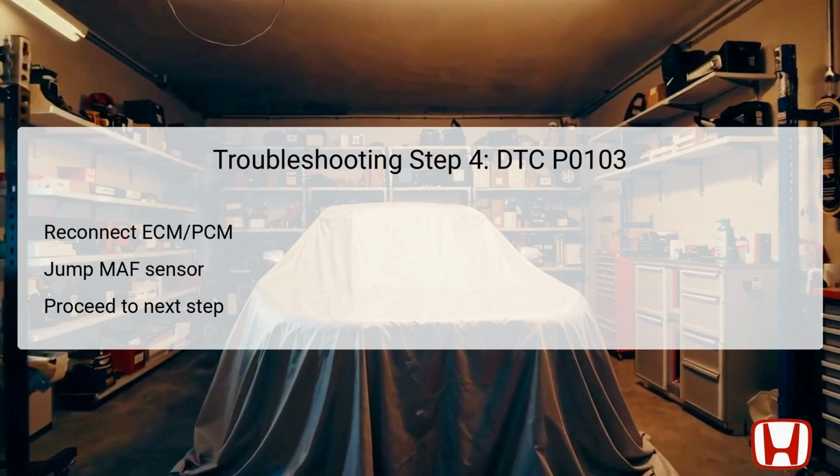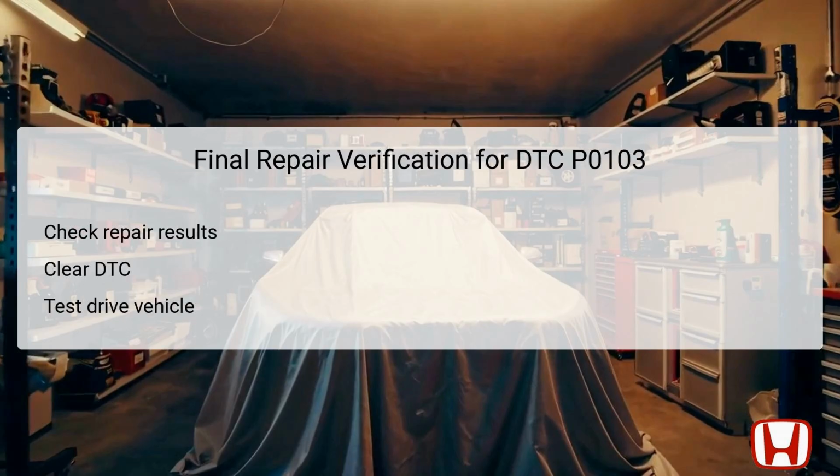Next, you will need to connect the MAF sensor/IAT sensor 5P connector terminals number 3 and number 4 using a jumper wire. This action essentially bypasses the MAF sensor and checks alternative circuitry to confirm whether the issue is with the sensor itself or the wiring leading to it. With this jumper wire in place, it allows the technician to isolate the problem, determining the areas requiring repair or replacement. After completing repairs, it is vital to verify the effectiveness of the work performed.